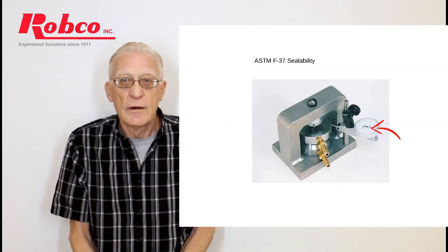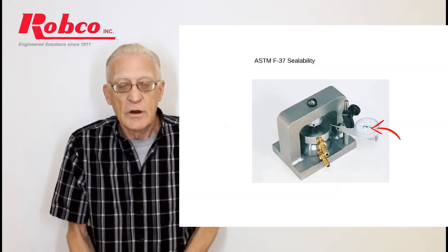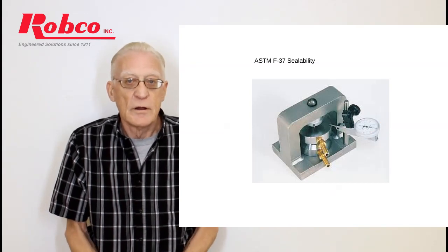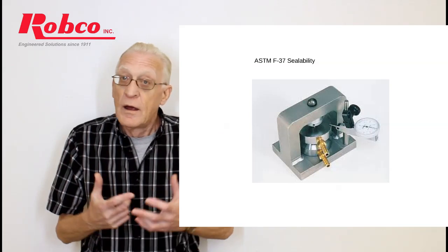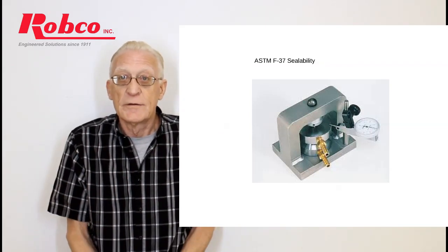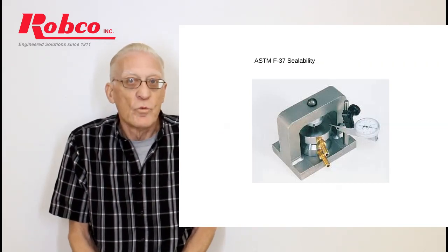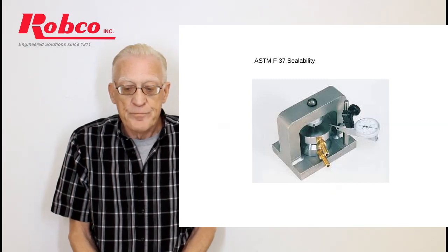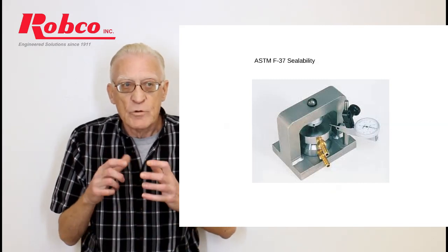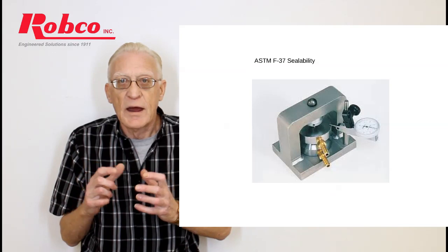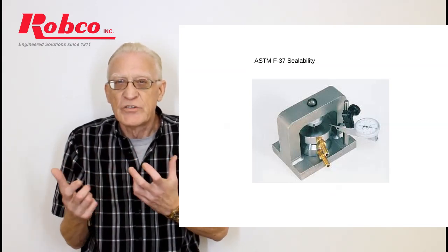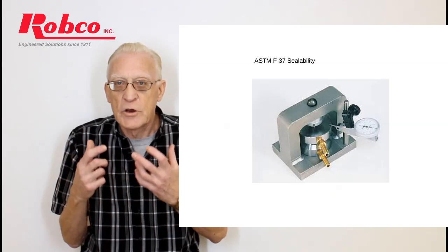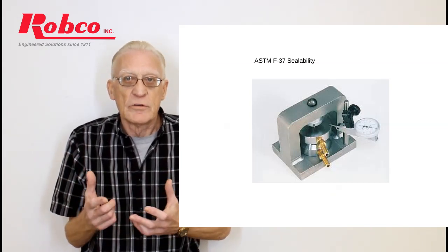They introduce X amount of pressure under X amount of load, and they calculate it. The gasket will leak across the face of the flange and through the gasket, and that's the North American way, if you want to call it. Not as accurate, but when you're talking about sealability and gas permeability, it's not leakage you can see. It helps us compare materials.